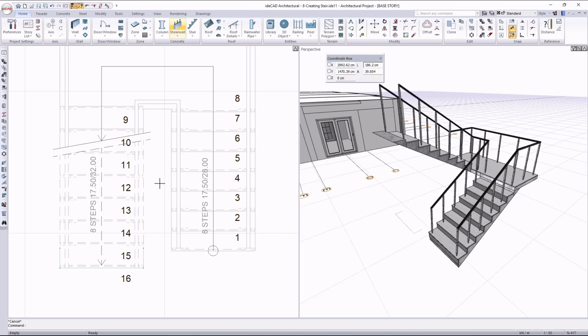For user comfort and safety, stairs should maintain consistent tread depths and riser heights. Inconsistencies can disrupt the rhythm of movement and may pose safety risks. Therefore, when deformation is applied, it is essential that this balance is maintained. Ideally, the required number of treads should be added to a single stair flight, and the landing elevation should be adjusted to ensure consistent dimensions across all flights.